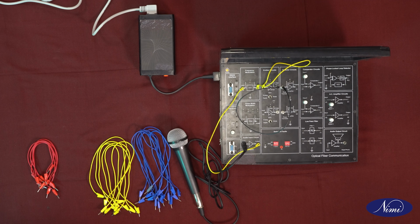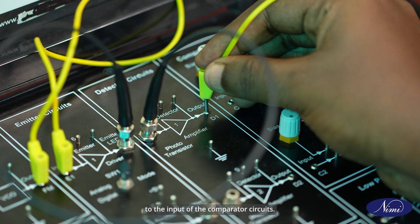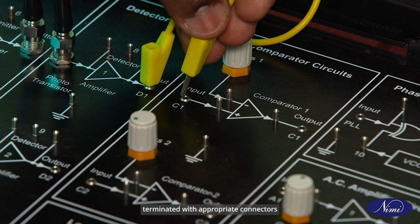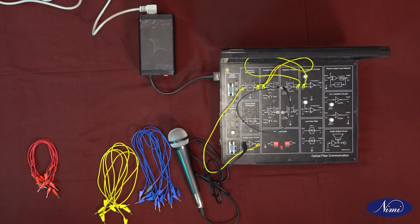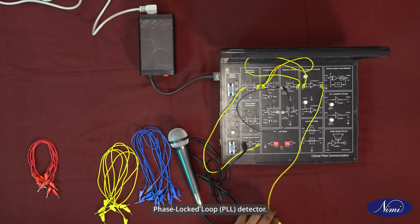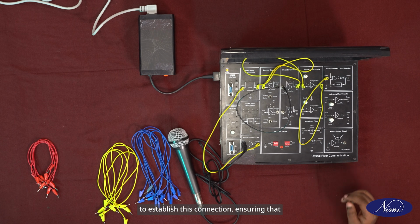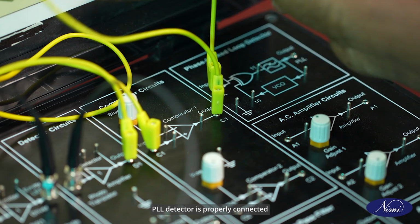Demodulation setup. Connect the output of the detector circuit to the input of the comparator circuits. Ensure that this end of the cable is terminated with appropriate connectors compatible with the input port of the comparator. Next, we will connect the comparator's output to the input of the phase locked loop or PLL detector. Use suitable cables or connectors to establish this connection, ensuring that the signal path from the comparator to the PLL detector is properly connected.